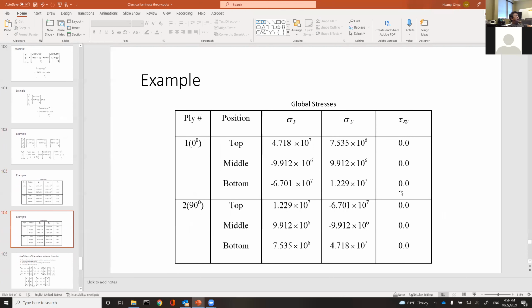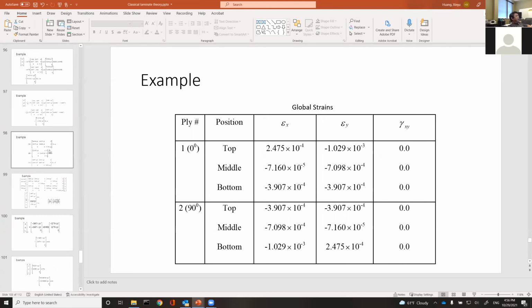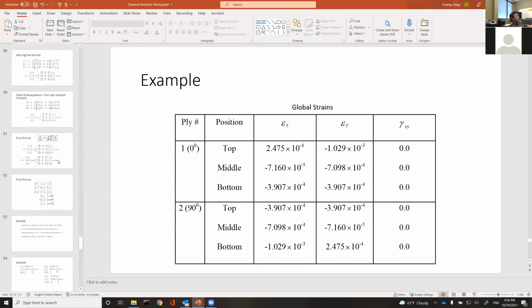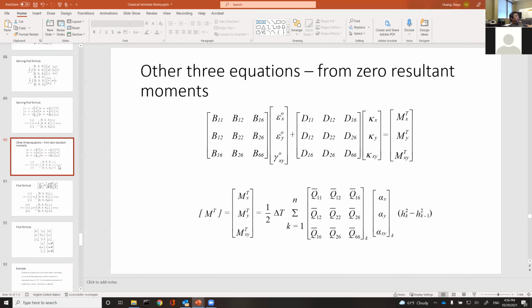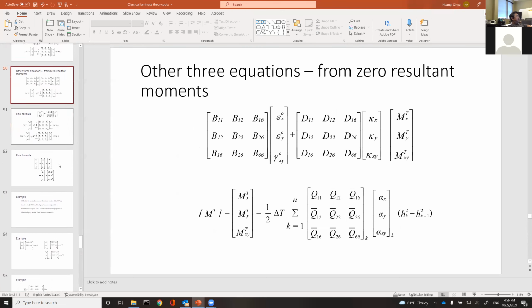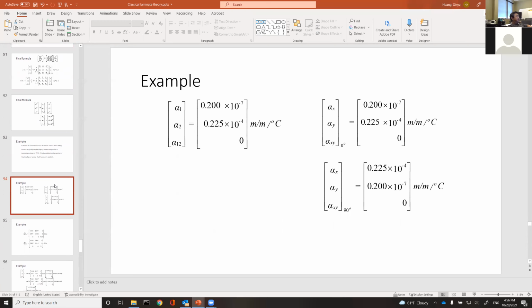When you combine stress, external mechanical load plus thermal stress, you superimpose. You put the load-induced stress together with the temperature-induced stress. That will be your total stress. All right, so that's basically the workflow. So start working on this now. We'll give some time, then we'll start solving some problems with thermal stress factored in.